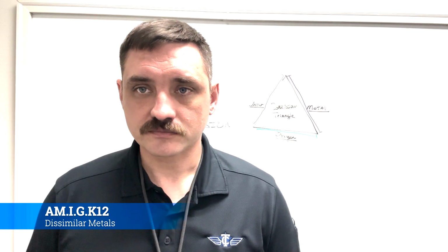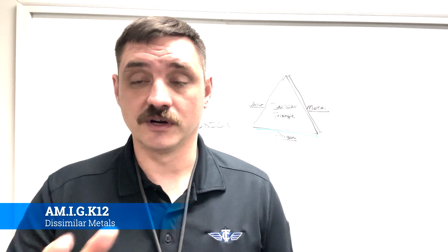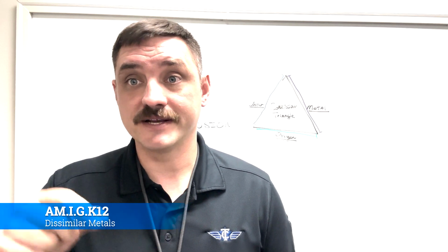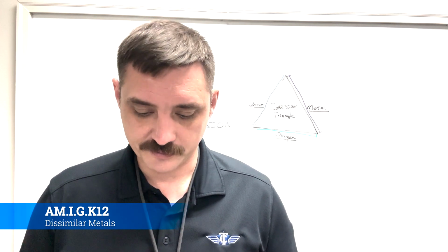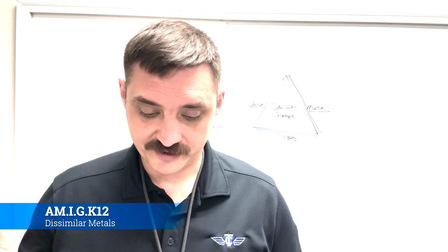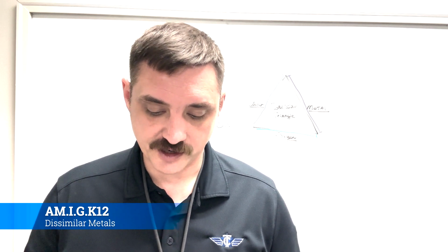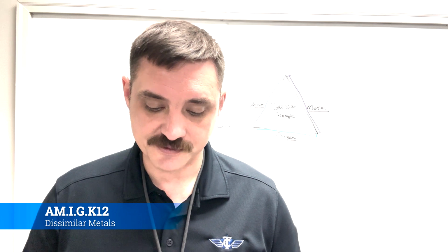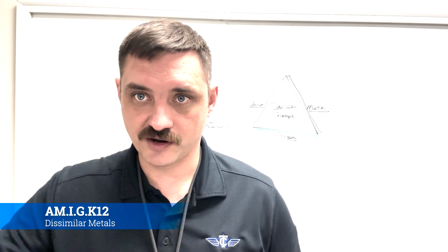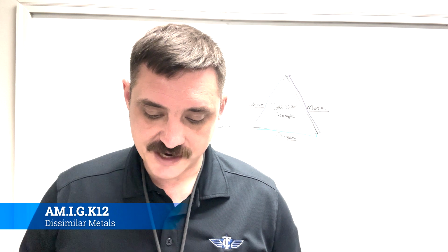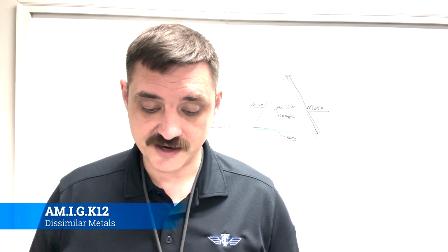The next one is zinc chromate for magnesium. Magnesium gets the two layers of zinc chromate plus a little bit extra. You'll have a layer of pressure sensitive vinyl tape that's 0.03 of an inch thick, applied smoothly and firmly to prevent air bubbles and wrinkles. To avoid creep back, the tape is not stretched during application, so it's put on easily and super slowly. When the thickness of tape interferes with the assembly of the parts, when relative motion exists between parts, or when service temperatures above 250 degrees are anticipated, the use of the tape is eliminated and extra coats, usually 3, of primer are applied.